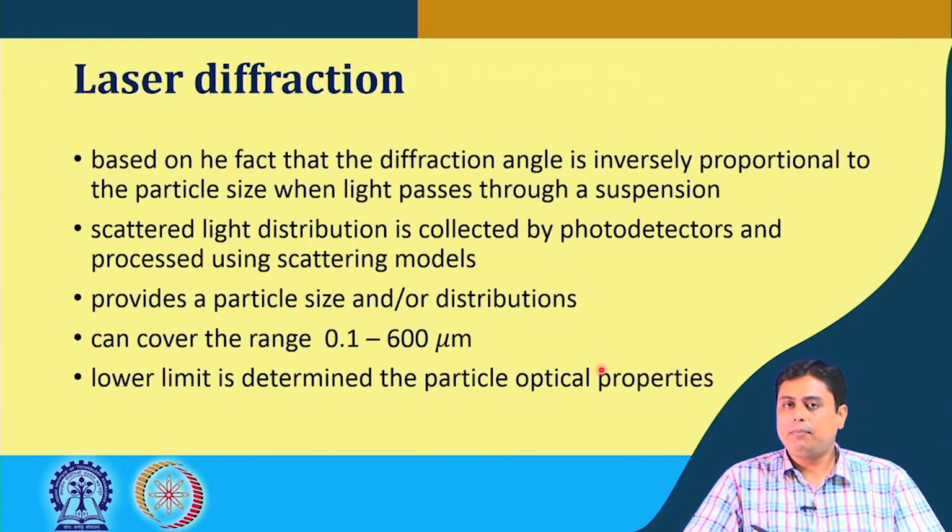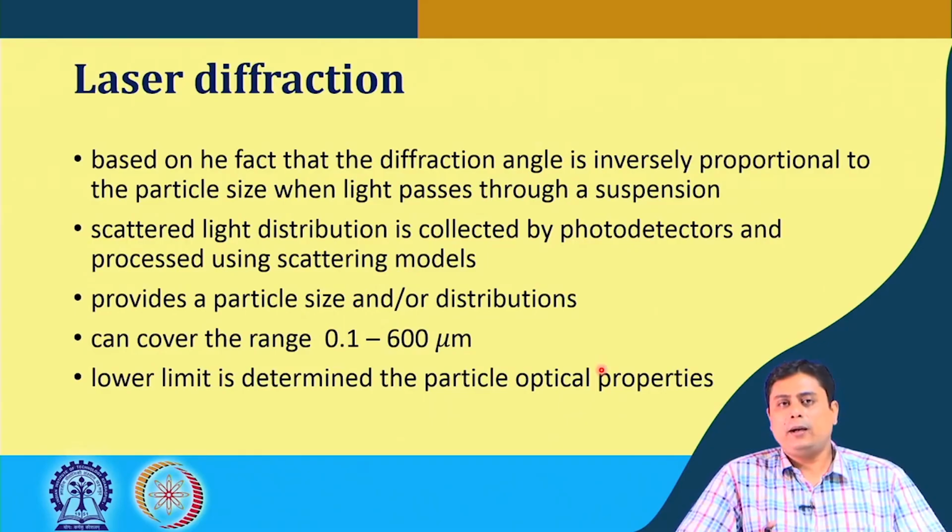If there is a single particle in the suspension and laser light is reflecting from there, you can determine a single particle, or if there are multiple particles suspended in a suspension, the collective response will give you the particle size distributions. By this technique, one can measure from 0.1 to 600 micron particles. The lower limit of 0.1 micron is basically determined by the particle optical property.